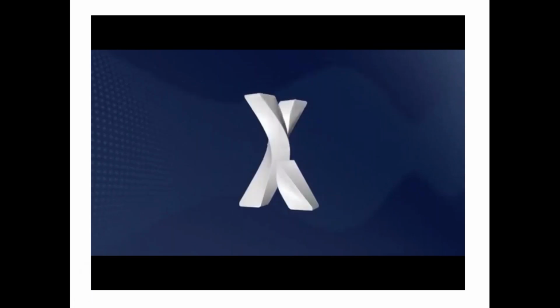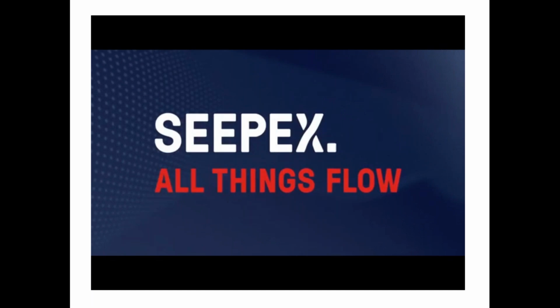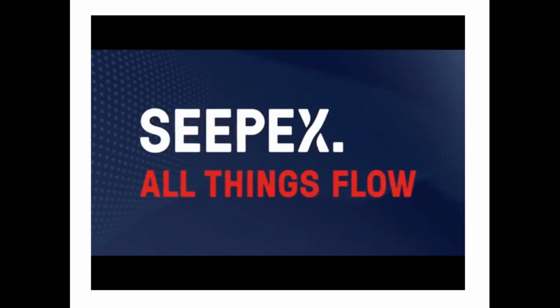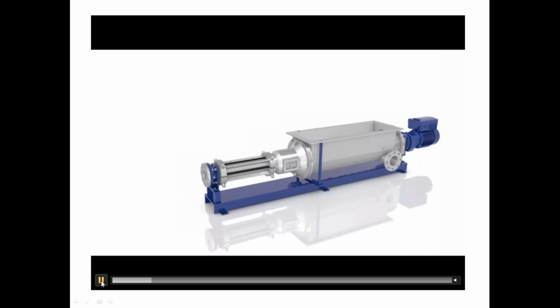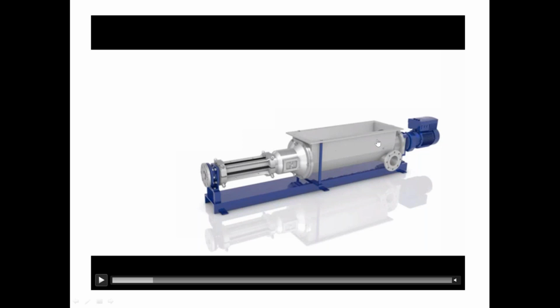So as I said earlier, I wanted to talk a little bit more about open hopper pumps and where the industry is going and how progressive cavity pumps are changing the industry as far as moving extremely viscous products, especially long distances. This right here is the newest product that has been launched by Seepex called Smart Air Injection. What Seepex has done is taken a typical open hopper thickened sludge or cake pump.